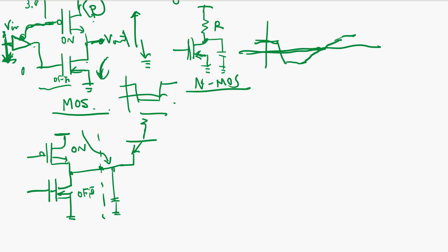But there's nothing to really accelerate this rise time, because the TTL is strange. It's a high impedance for high. Low is not the high impedance.